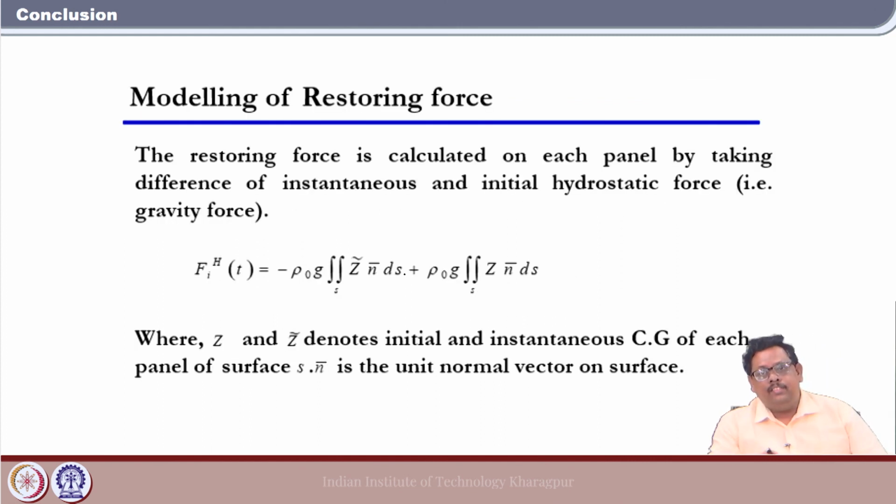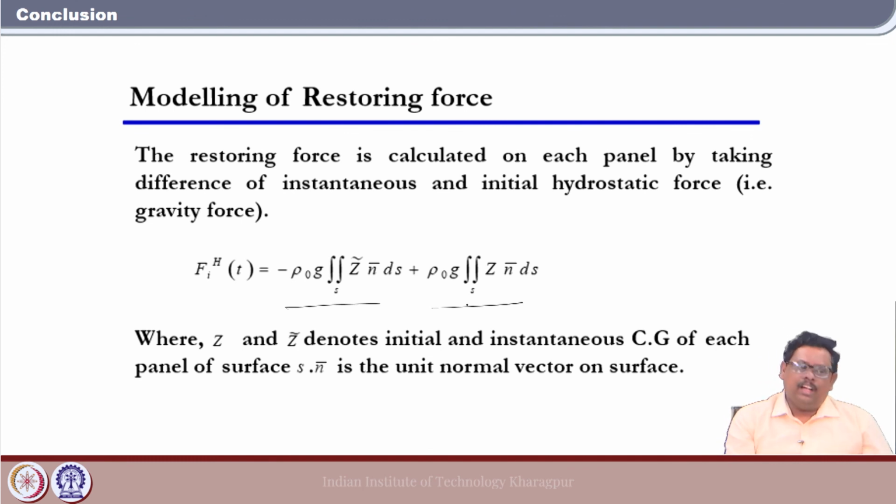Now, the restoring force is also very important. In the case of hydroelasticity, it is not the same as for the rigid body. Here we can calculate the hydrostatic force as the difference between the instantaneous hydrostatic force and the initial hydrostatic force. This is how we normally calculate the hydrostatic force at that particular time.